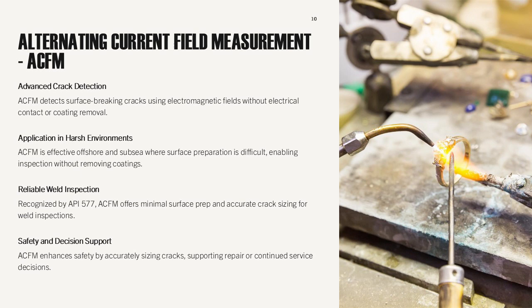However, ACFM requires specialized equipment and trained personnel. Its applications include inspecting welds on pipelines, platforms, and pressure vessels. The technique enhances safety by providing accurate crack sizing, which supports informed decisions on repair or continued service.